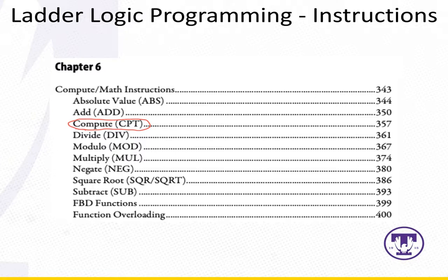However, in here you're not allowed to use it because it sort of takes away from you having to think about how the PLC is going to scan the various math instructions and where you're going to store the result of those instructions. So in here, you're not allowed to use the compute instruction. Don't do it. Other than that, the rest of these functions are available for use.